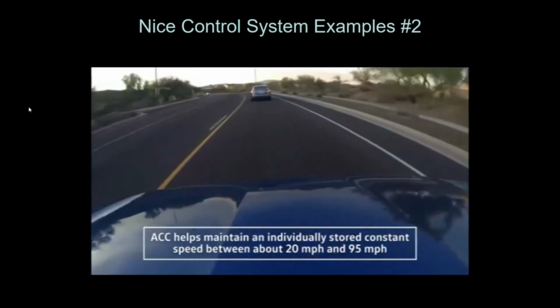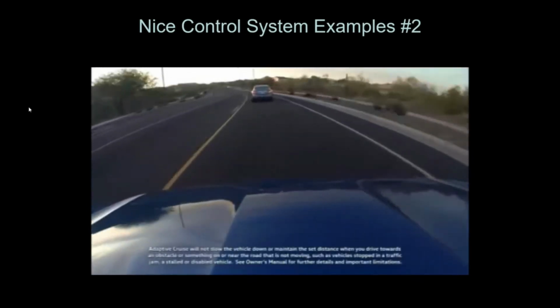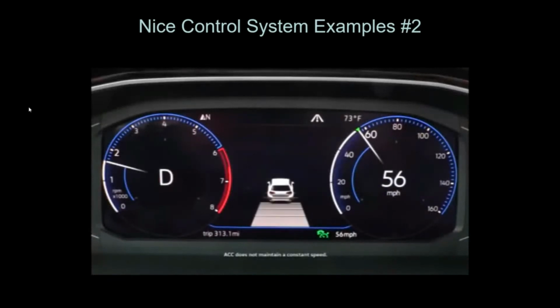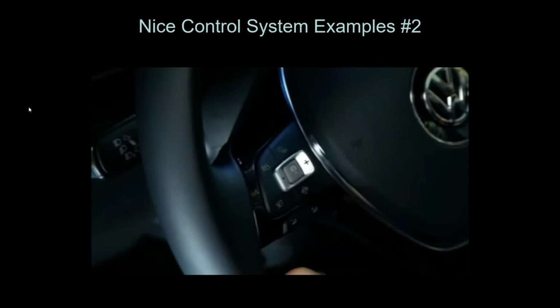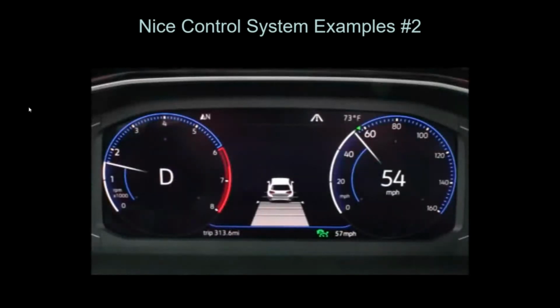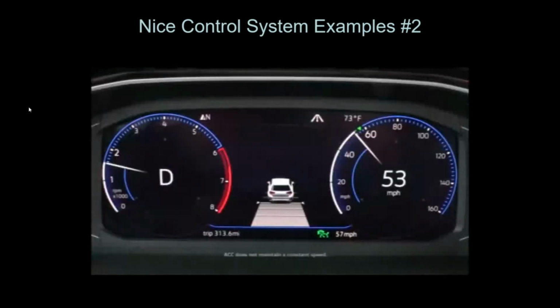The adaptive cruise control system helps maintain the following distance by determining a time interval, resulting in a speed-dependent distance. When adaptive cruise control is active, the following distance to the vehicle in front can be adjusted to one of 5 positions by pressing the adaptive distance button. The distance intervals can also be set using the plus or minus buttons immediately after pressing the adaptive distance button.